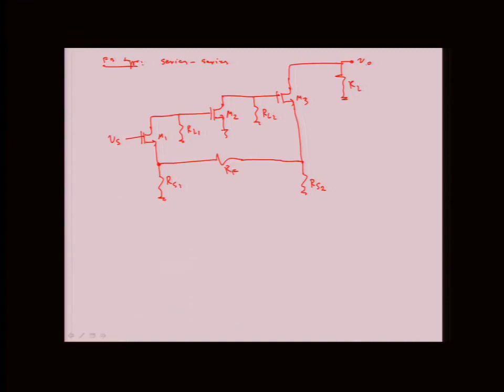Okay? And when we do the output impedance, R out, how would you have done the RR, the return ratio, with output shorted or output open? You could guess that one or the other corresponds to the full return ratio, right? So if you open, then you could say, well, in a shunt, open is good.